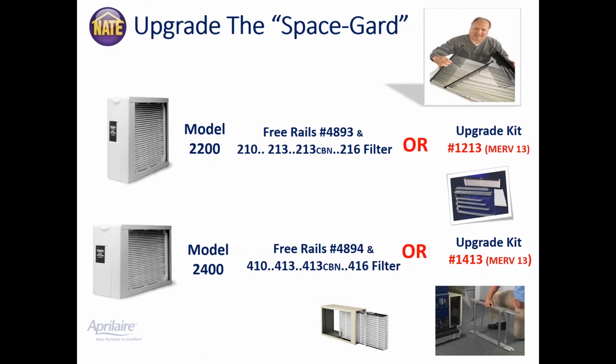So what we've done is we've designed a couple upgrade kits, the 1213 and the 1413, to allow you to upgrade a 2200 or a 2400 to use our current pleated filter media. So you take out the pleat spacers, throw them away. Take out the inner housing, throw them away. Put in this metal framework. It's just 6 pieces like you see there into the cabinet.